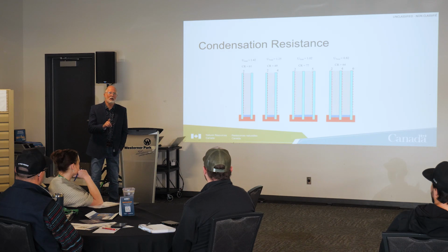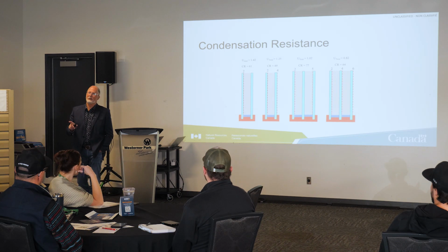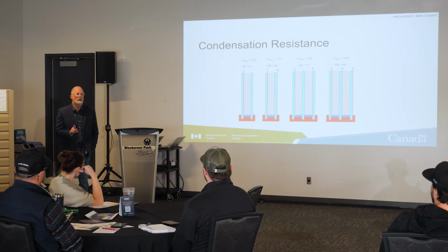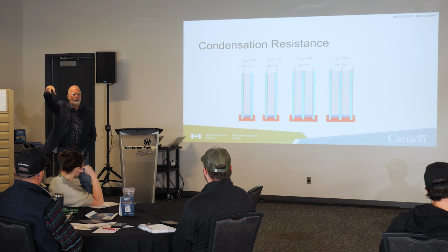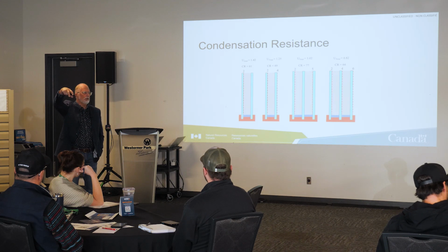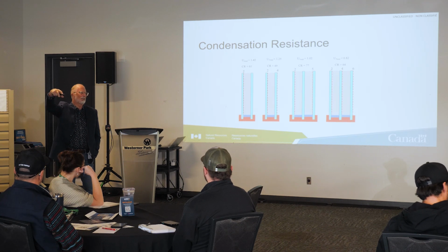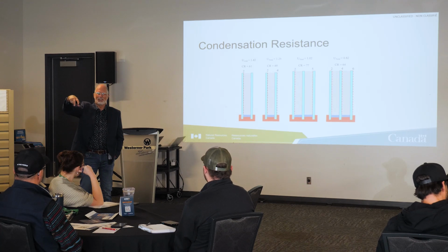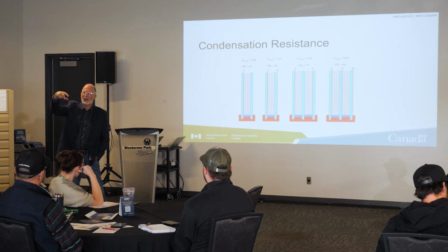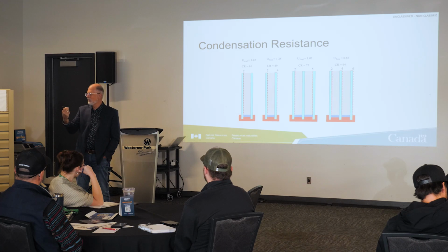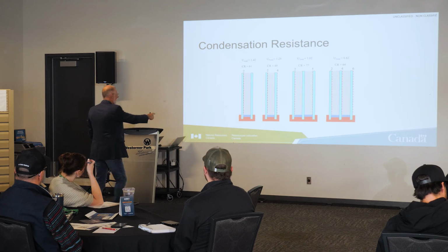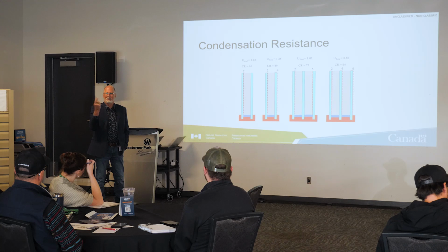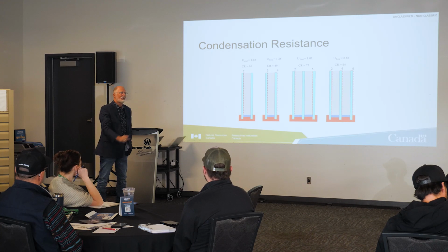When your homeowner has frost or condensation on the window, what's the simplest way to eliminate it? Air movement. What's the middle of the house, 35 degrees or 30? It could be 35% at 21 degrees. Does that air have potential to absorb moisture? Absolutely. How do you get it at the glass over there? You open the curtains, you get the air movement, you turn the ventilation fan on, you get circulation going.